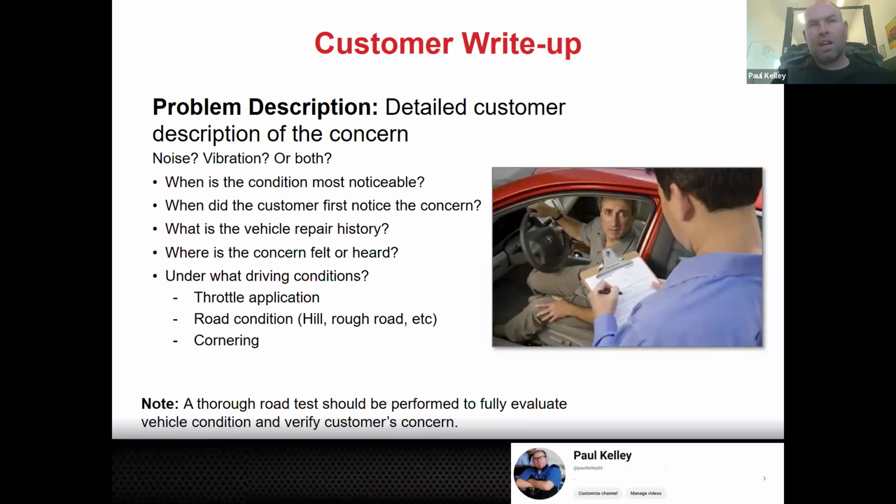If they say, I hear a vibration, you say, no. Hearing is your ears. Feeling is like, what do you feel? And try to help them narrow it down. When is it noticeable? When did you hear it? When did it start? What's the history? Has it ever done this before? Have you had any recent work? What are you doing? These are important things.